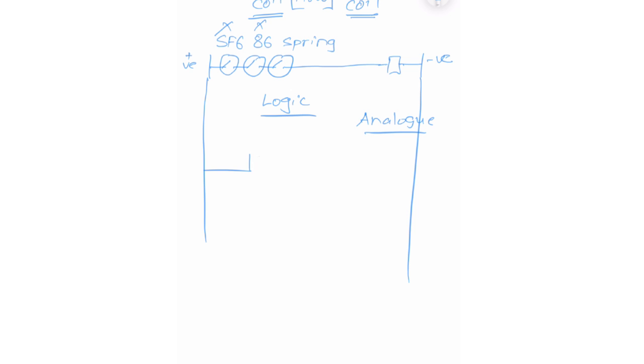Then we will check the actual gas pressure through a mechanism called switches. These switches will operate when the gas pressure is actually low. This input is given to a contact multiplier. This contact multiplier will have different contacts like open contact and closed contact. Each of these contacts is used in logic for various purposes. Today we will see how it is used in a closing circuit.